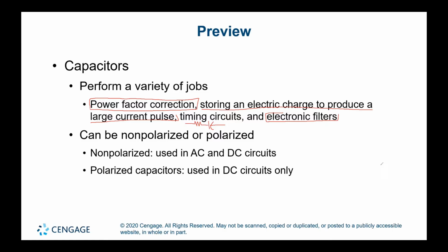So if we have a load here, okay, and we are going to be connecting a capacitor here, it is very, very important that if that is the positive terminal and this is the negative terminal, we have the same polarity on both. And I already told you what's going to happen if we don't do that. We're going to see lots of oil.